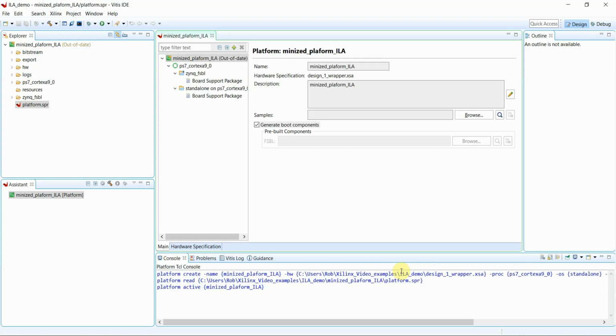Now the way that this board was designed, the UART that's actually tied to the UART to USB bridge is UART 1. So what we need to do is change the board support package so that it specifies UART1 as standard I/O, so that when we write out hello world, we'll get the data going to the right UART.